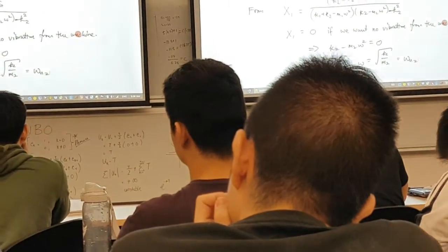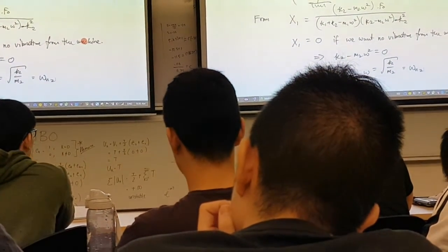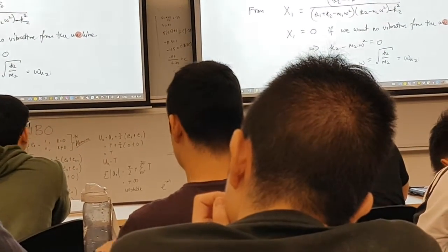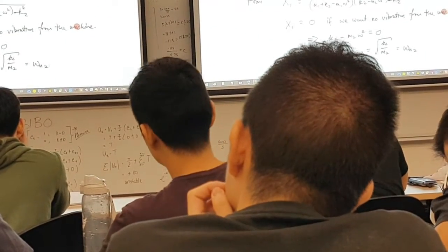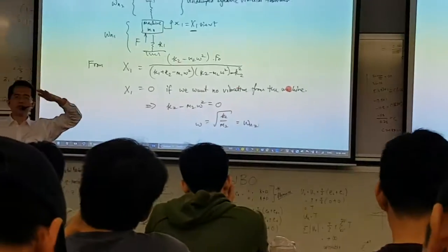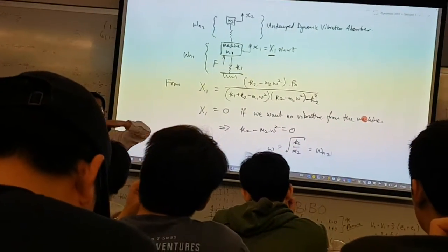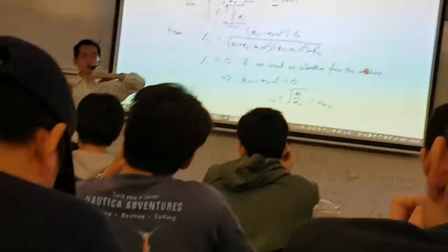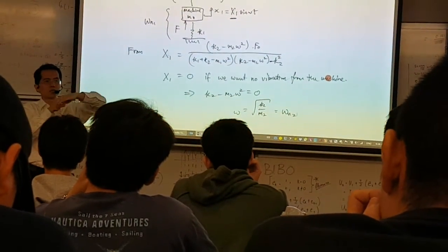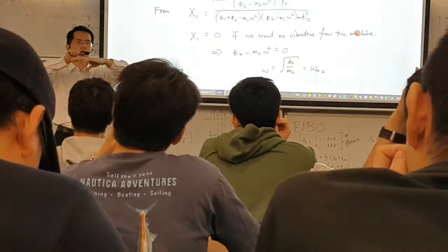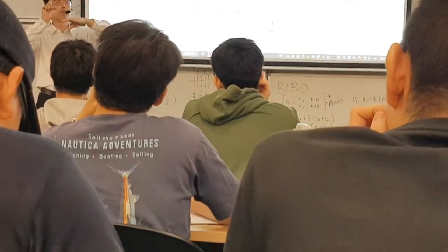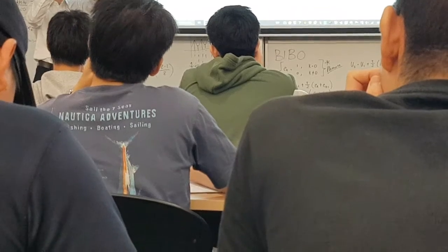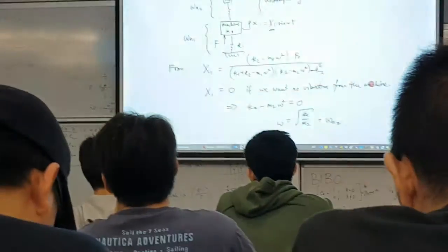Not sure if you've seen some of the bridges. Sometimes in the bridges they have things like a damper and then a mass, because your bridge may resonate at a certain frequency, as a single degree of freedom system. In order to prevent that from resonating, you add on a special attachment to bring away that resonance, so that this thing that you attach to it starts to resonate instead of the bridge. Right? So it's a safeguarding feature you can use.